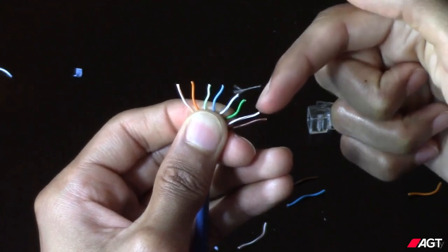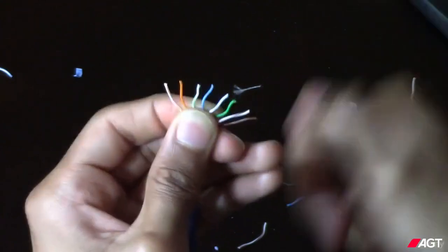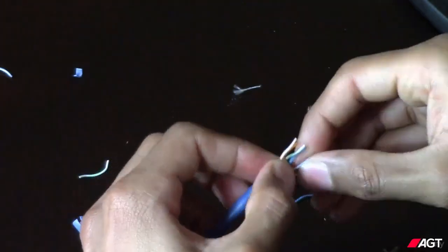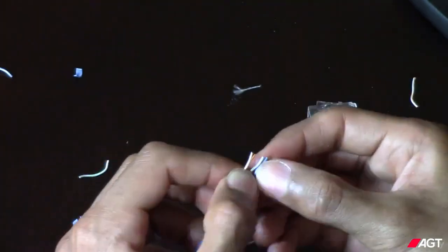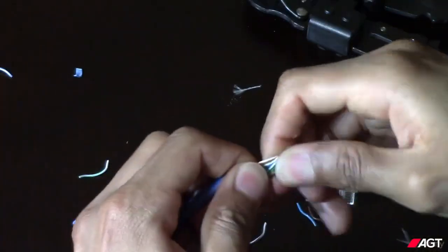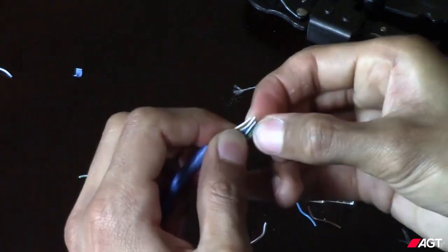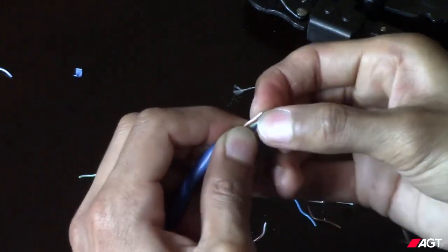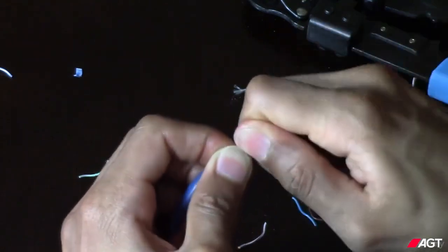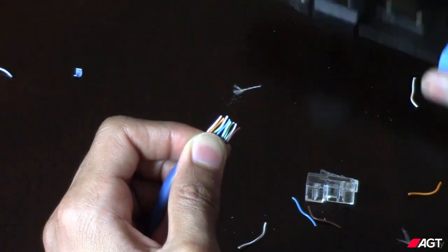and brown. Once you've got them in the proper order, the next thing you'll want to do is group them together, as close together as you can. Grab them by the end and give them a few gentle bends to ensure that all the wires are neatly flattened. All 8 wires have to be in a neat row in order to fit into the connector. Give the colors a quick review and make sure they haven't shifted.